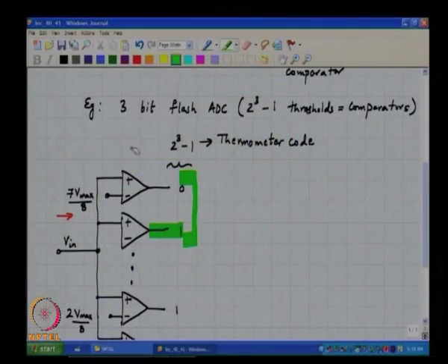and as we know, usually you would like to sample and hold the input and then work off that sample, which is what you are trying to quantize. So the circuitry which drives the array of comparators has to drive a larger and larger load as the number of comparators keeps increasing. So for standalone flash converters, typically 6 bits is a break even point. Beyond that, people either explore ways of avoiding the flash converter, or try some innovative techniques to keep the number of comparators low while still giving the resolution you want, maybe 7 bits or 8 bits. But standard flashes are usually limited to about 6 bits, as you will find out if you browse the literature.